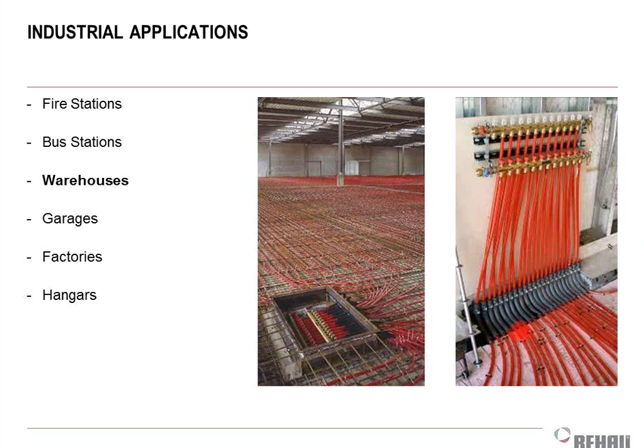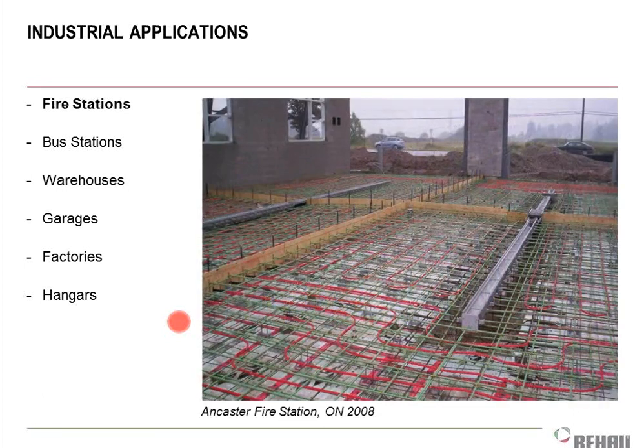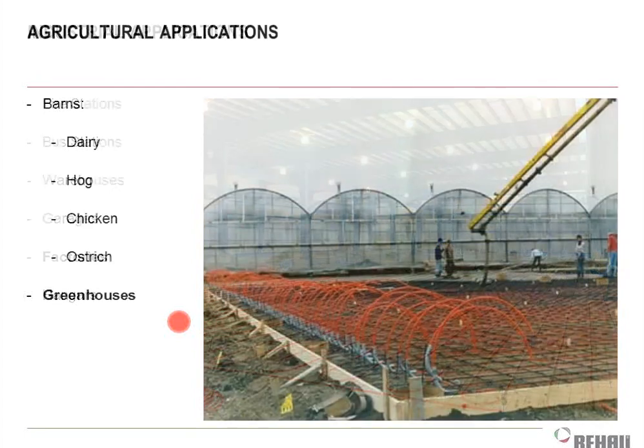But we'll lay out all these circuits on the floor. We'll help you design the circuits and kind of plan them out. Like we said before, bus repair terminals are a common application. Fire stations, almost every fire station we've done in the past 10 years have had this. Right? The fire truck leaves. They leave the door open for whatever reason. All the heat gets sucked out. They come back 25 minutes later after the false alarm and pull in. Well, the radiant floor keeps that heat way longer than the air would. Airplane hangars, also fairly popular, that kind of stuff. Anytime you got doors opening and closing a lot, it becomes more of a no-brainer to do radiant-based floor. So these are just some of the institutional type applications that we just mentioned.